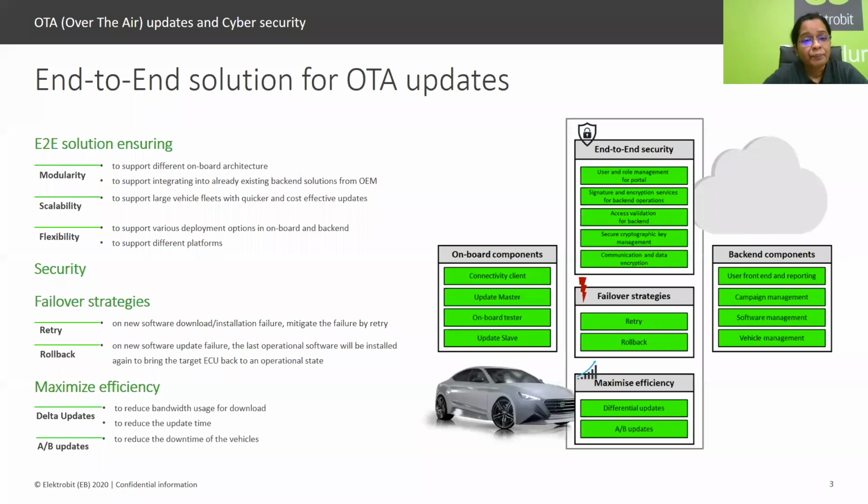Along with this, we also have today the mobile industry trying to gain business in the automotive domain for the OTA updates. For a mobile, there will be hardly one or two chips where the updating of these two chips will not be that difficult. But it's not the same for the vehicle. In the vehicle, there are multiple ECUs. The dependencies of the ECUs have to be addressed before the OTA updates happen. Hence, the OEM has to also rethink while going for the solutions which are coming from the mobile industries.